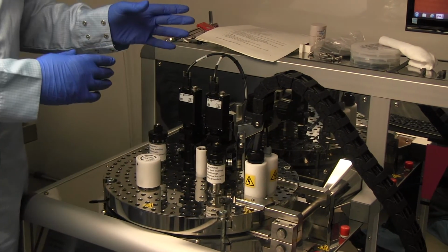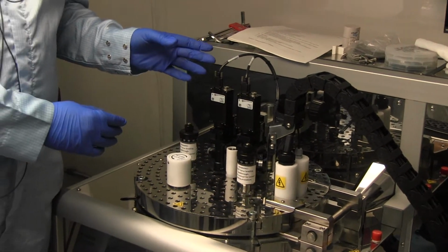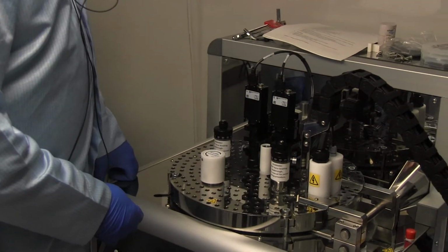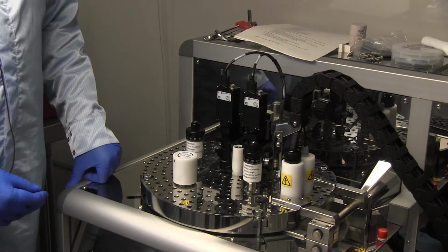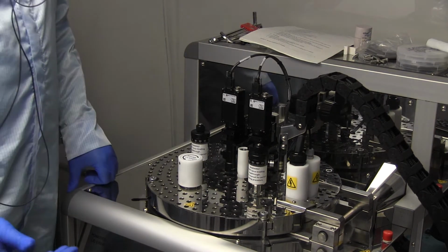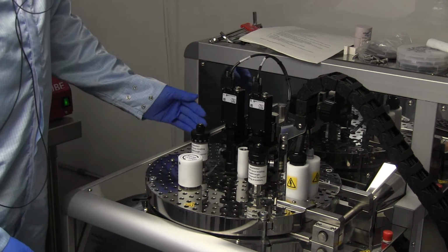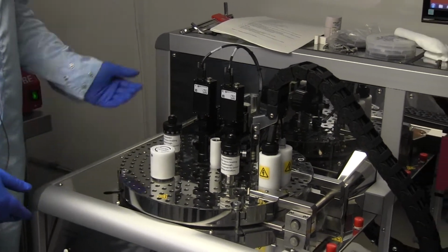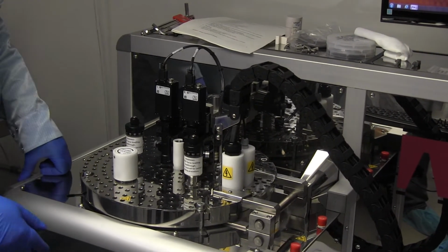We don't want to vent the pump while it's spinning because that can damage the pump. So it's there to protect the pump and also save you time, because you don't want to be waiting for the pump to stop because it takes a while. So you can shut the valve, vent the chamber, then take your wafers out while the pump controls itself.